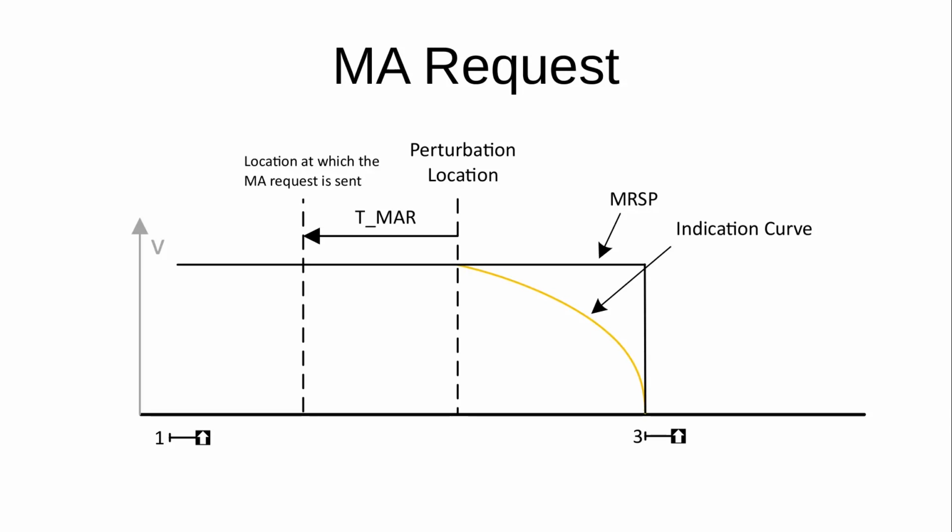This is a problem if the end of authority and the supervised location are close to each other, because the braking curves calculated for the supervised location are supervised with the maximum front end, but for the end of authority with the estimated front end. To solve the problem, the trains equipped in Denmark according to SRS 340 deviate from the ETCS specification and also send an MA request at the pre-indication location calculated for the supervised location. This is also the way how it is solved in SRS 360.